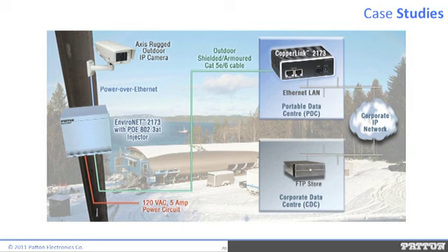When Enbridge came to us for a solution, we used our custom environment enclosure along with a third-party extended temperature PoE power injector and our own extended temperature Ethernet extender to allow for Ethernet connectivity of over 1,000 feet. The PoE injector was used to both power the camera and its internal heater and fan. The environment enclosure protects it from the elements.